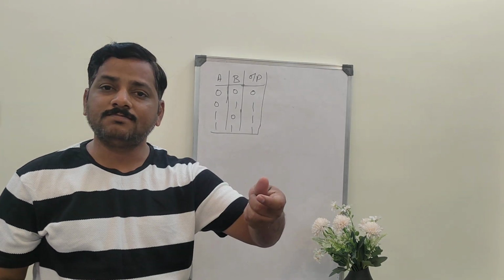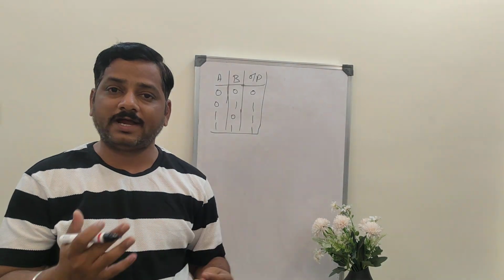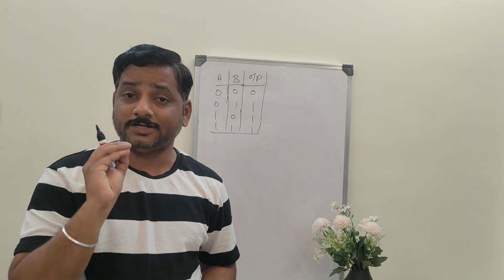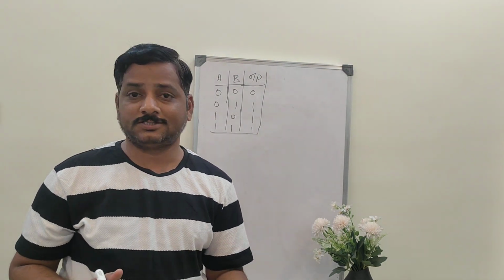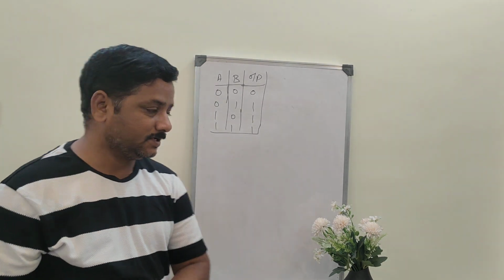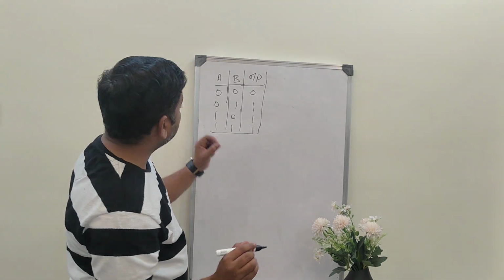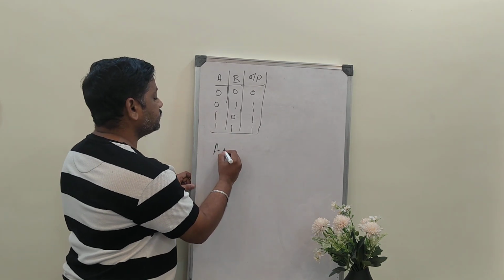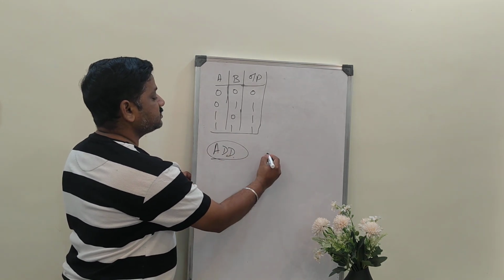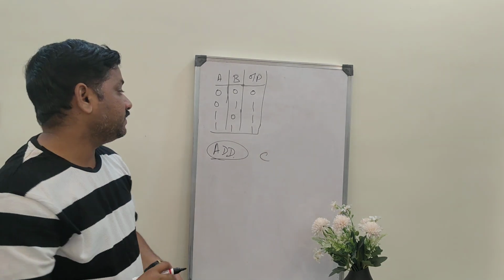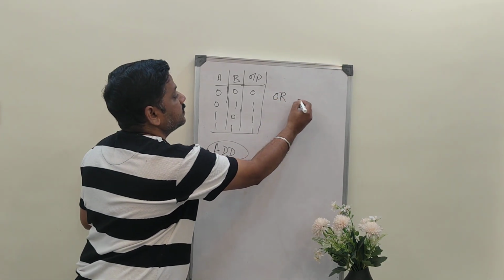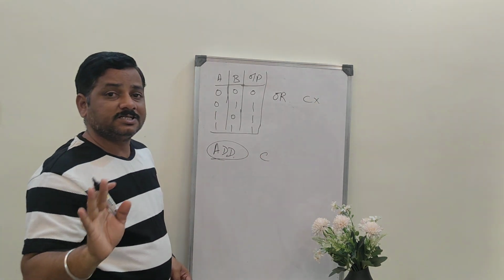So if you want to add numbers, you can OR it or add it, one and the same. But there is a slight difference. If both are the same, there is no need to have two instructions in a microcontroller. The difference between ADD and OR is that when you execute an ADD instruction, there is a chance of affecting the carry, a chance of generating a carry. But when you go for an OR instruction, no carry will be generated.